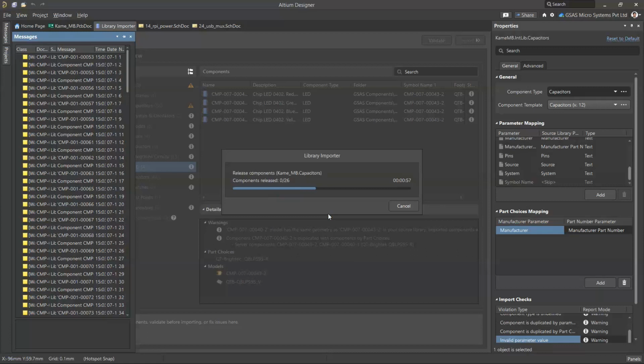And if you have any components which have an issue that you need to rework, you can upload them, or you can ignore those components from updating to the Altium 365. Like I showed, we can have a few uncategorized components. The reason I am unable to assign them is that the category type is not available. That's the reason I ignored them. But we can just go back to the A365 and create one category and create one template and assign them appropriately.